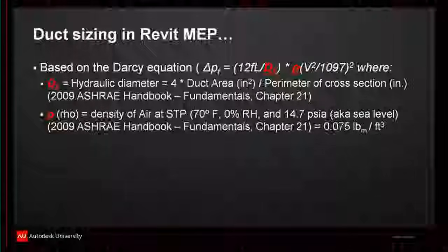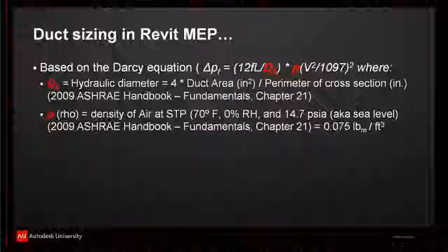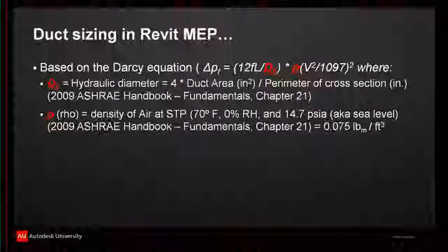What's rho based on? Well, remember, rho is based on the standard temperature, standard pressure of air. And that's straight out of ASHRAE. And if you remember, we talked about this. What was the number that we had on that ductulator? Basically, the 0.075. So again, the ductulator says 0.075. Rho for the calculations for Revit MEP is based on 0.075. So again, we're still in sync. Okay, so hopefully by this time the engineers are feeling a little bit more relieved. We can actually begin removing our hand from their hand and helping them stand on their own.